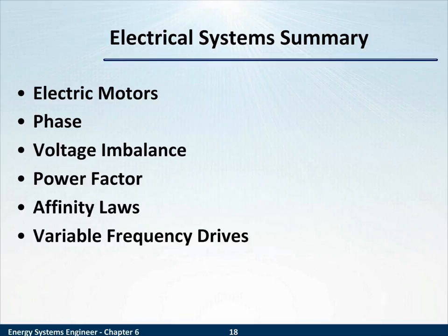Some of the main topics were the electric motor itself and the idea of single-phase, dual-phase, three-phase, and how that affects the amplitude and how voltage imbalance can occur if those phases aren't in phase, and the effect of voltage imbalance on efficiency and derating. We then talked about power factor, a very important concept, particularly if you have a power factor penalty by your utility. Now you understand why they've put that penalty in, and you understand how to solve it and whether the solution is cost effective.